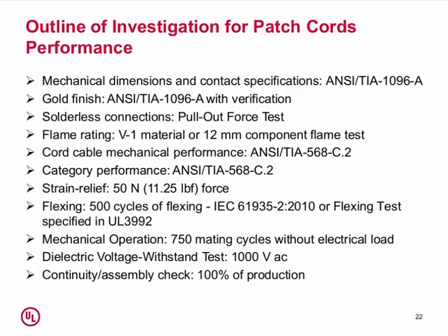So there are two options, and this is one of those cases where, depending on where you are located in the world, what kind of test setups you might have at your facilities, these are two tests that are similar, but not exactly the same, but either one proves whether or not a cable can withstand a certain amount of flexing without pulling out or damaging the connections. There's a mechanical operations test, basically 750 mating cycles. There's no electrical load applied.